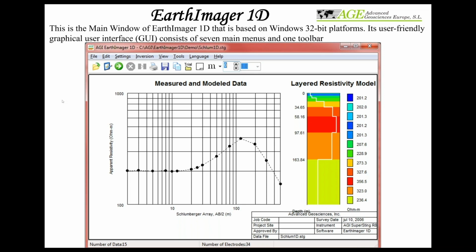Sometimes what happens if you're too close, especially for current electrodes close to potential electrodes, is that your current is injecting lots of voltage at that point. You have a good contact resistance, and you're injecting almost 400 volts, but with a very small spacing, voltage saturation can happen. So that will give you some error.